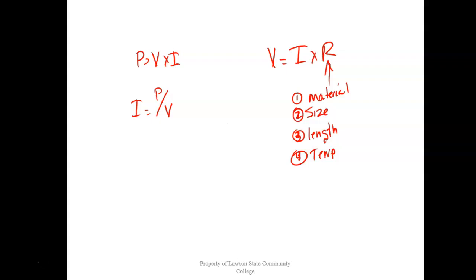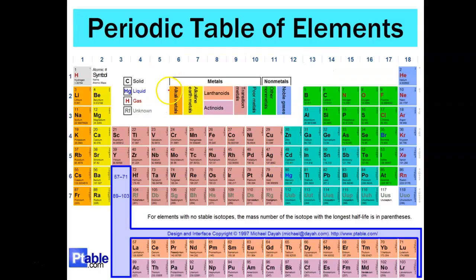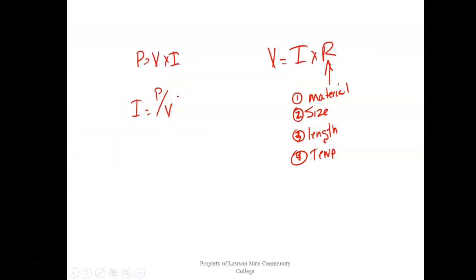low current things. So what we're saying over here, if I'm trying to sell you 1,000 watts, and I do that at 10 volts, then that's going to require 100 amps, right? You understand that? But if I do that 1,000 watts at 1,000 volts, then I'm able to provide that to you at 1 amp.